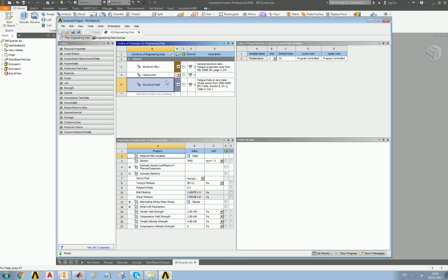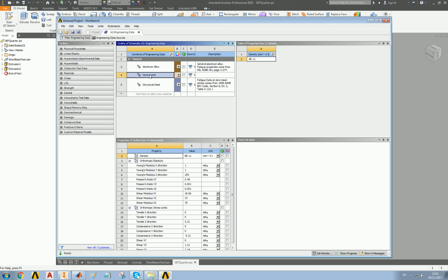So now we have our 3 choices of material, and the thing to notice at this point in time, more important than anything else, is the directions of the Young's modulus. Honeycomb is easy to collapse in 2 directions, but the 3rd direction is quite stiff. It's not as stiff, of course, as solid steel, but it's still impressive. So these are the 2 directions given, I think, arbitrarily low stiffnesses, but they're very much smaller than the key 3rd direction, which is in the Z direction. So that's important.